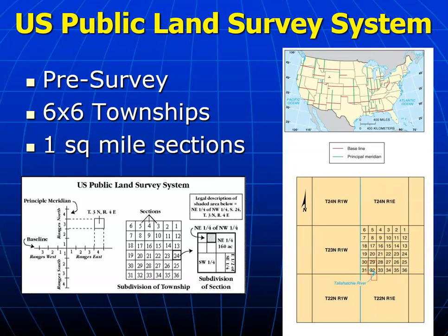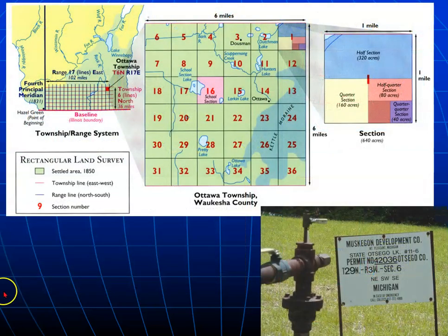In the 1992 movie Far and Away with Tom Cruise and Nicole Kidman, when they're going to get their parcel of land and identify it, it's tied to using the public land survey system. So again, surveyors would understand what this says: this is Township 29 North, Range 3 West, which means it's the 29th township north of the baseline. It's Range 3 West, so it's 18 miles west of the principal meridian. It's whatever 29 times 6 is, miles north of the baseline.